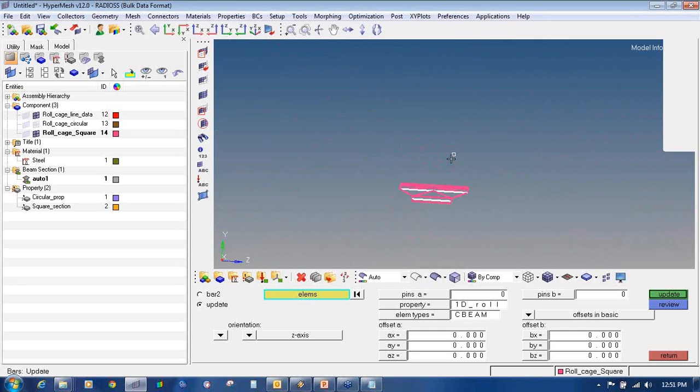As you can see, the orientation stands for along which axis you want to orient. The cross section is in the YZ plane, and the length of this particular beam is in the Z axis. So I have to orient this into Y to define the cross section. You just define the axis as Y. Always select any axis perpendicular to the length for the orientation, so the cross section will get defined.